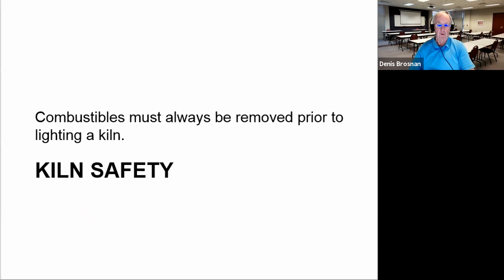Now, in your experience, this is no different than people that work on sewer systems, right? Or other areas where there may be combustible gases. Guys go into a sewer system, the first thing they do is stick a combustibles meter down into the sewer system to make sure it's safe to go down there. If it isn't, they're going to have to add an appropriate amount of air so that they're below the lower flammability limits on the sewer gases that are there.